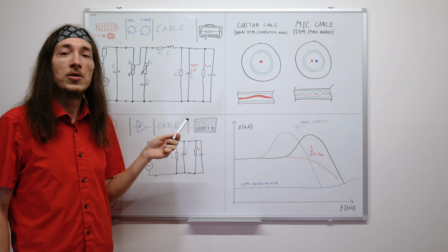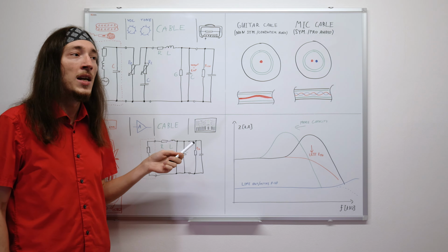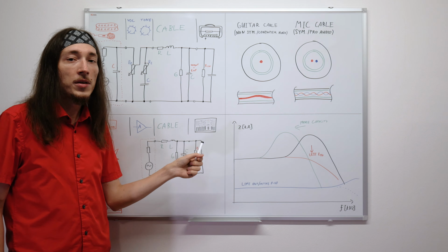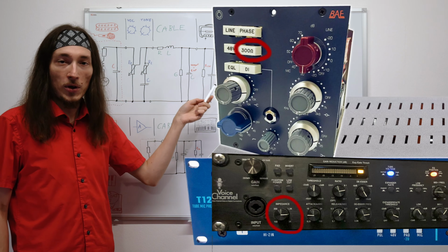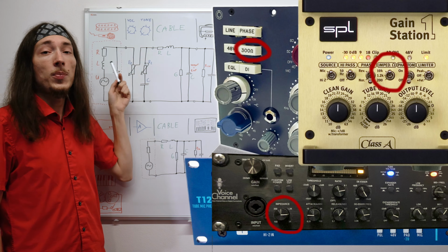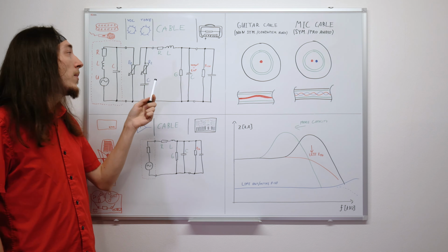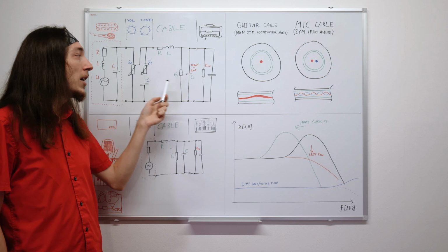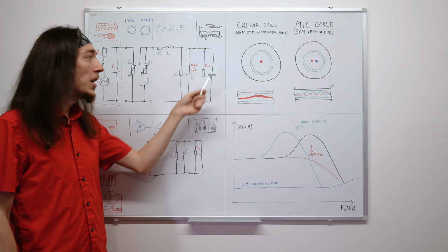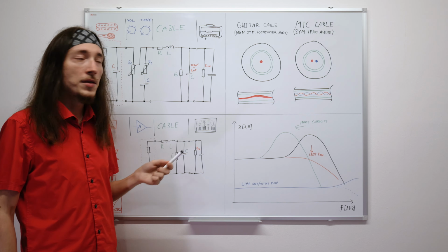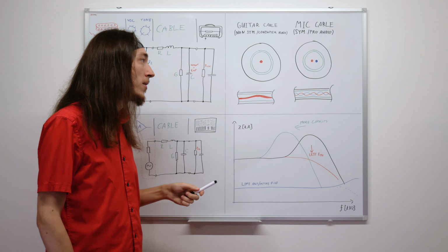And for these situations, especially mic preamplifiers have switches or potentiometers for tuning the input impedance of the mic pre. In the case of guitar pickups, we most of the time have the tone controls, or we can use a different length or type of cable. Now let's take the cable back into the game and let's talk about the different constructions.